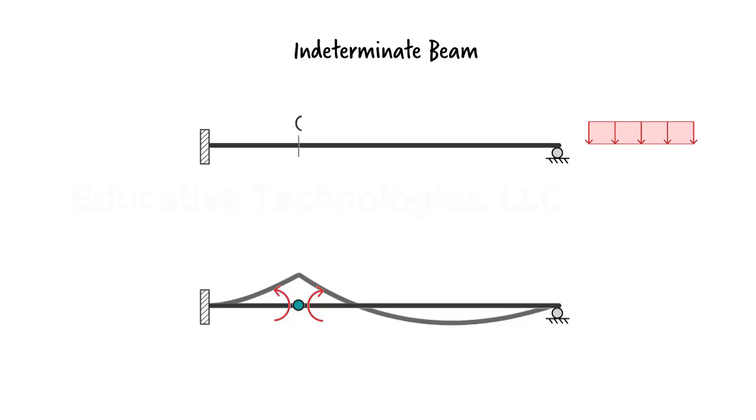To do so, we need to be able to locate the point at which moment at C changes sign. That is, we need to know the exact location of this point so that we can determine the required length of the distributed load and its position on the beam for producing maximum negative moment at C. But this cannot be done qualitatively. We actually need to formulate a mathematical expression for the nonlinear influence line in order to determine its vanishing point. Let's see how that can be done.